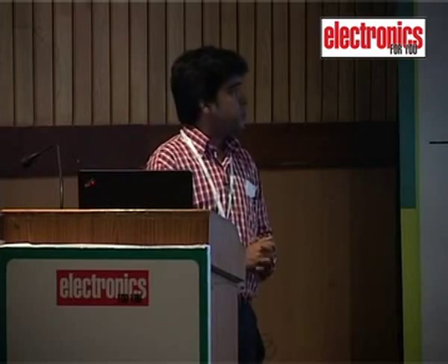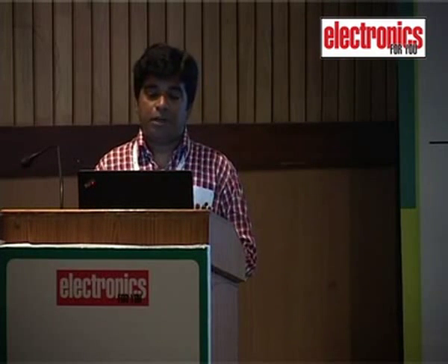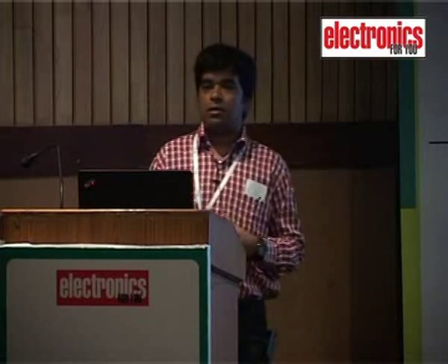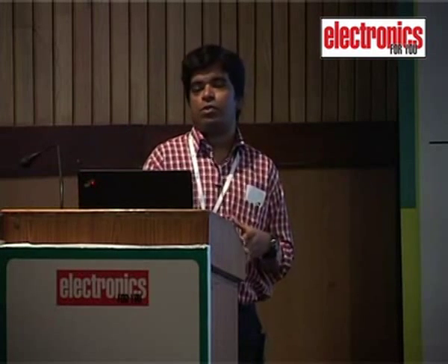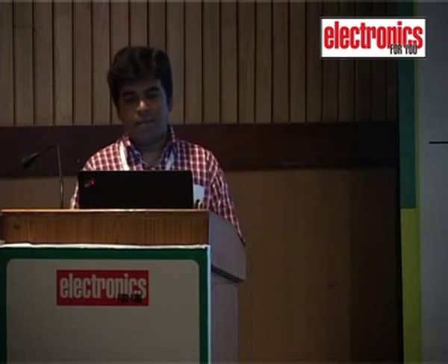Now from the implementation perspective, let's first understand the image. If the image is typically 24-bit, we need to convert it into 8-bit color. Why do we want to do that? Because our ROM is byte wide, so any ROM data being accessed will be 8-bit wide. With that in mind, we need to compress each pixel from 24-bit into 8-bit.